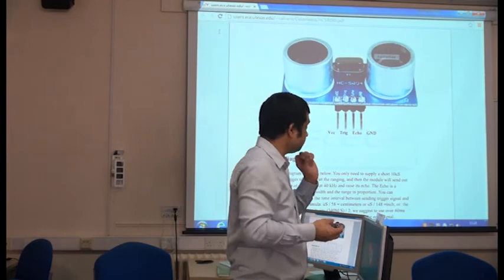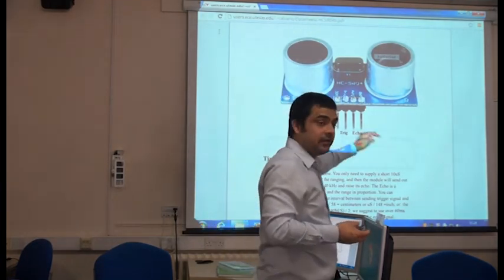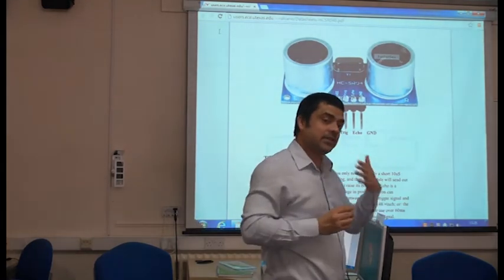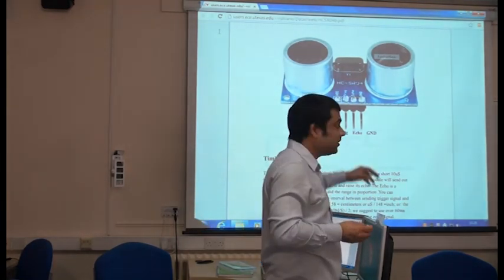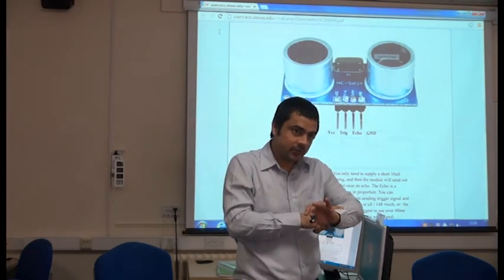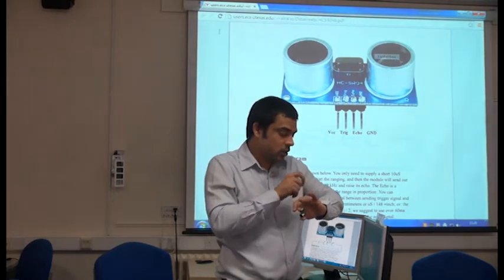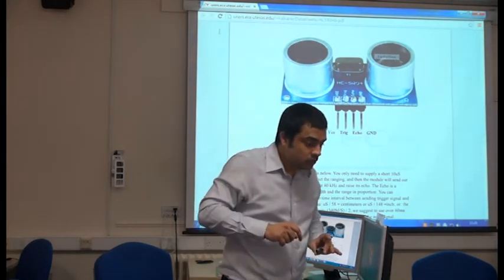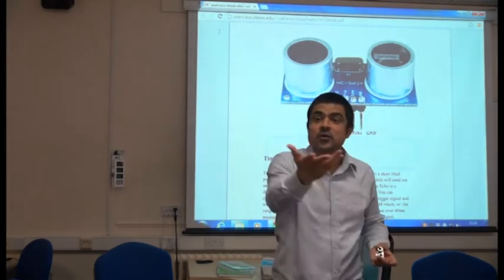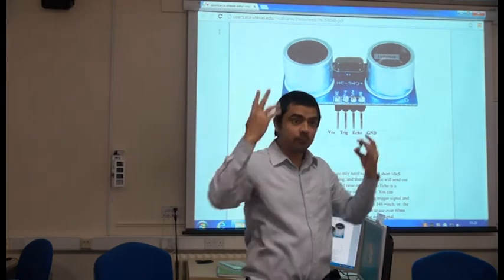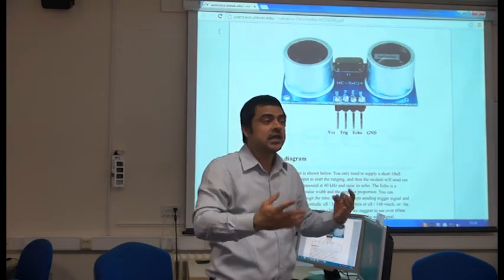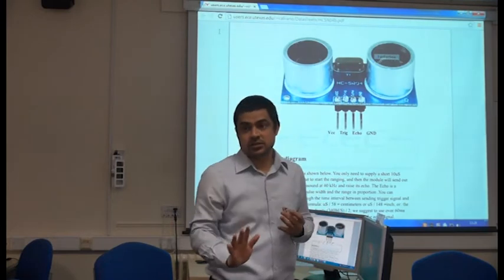No? So effectively, you've got trigger and echo. Trigger is a transmitter, it sends a packet. Echo is the receiver, it receives the packet. When you make the trigger pin high, that time it throws a packet, and then you start ticking. You start recording the time, and then you keep a watch on the echo pin and find out, maybe you put a LED on echo pin, and when the LED is on, that means echo pin is high. Echo pin is high, that means echo pin has received the hello message.